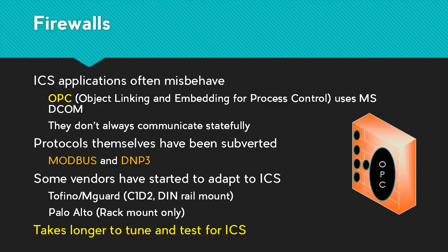You're going to take a pretty firewall and you're going to punch a lot of holes in it for little things and this one gigantic gaping hole for OPC. The protocols themselves that the industrial systems communicate on have been subverted. Modbus just has no functionality for authentication, for validating that a command that you pass it is valid or is proper or anything else.